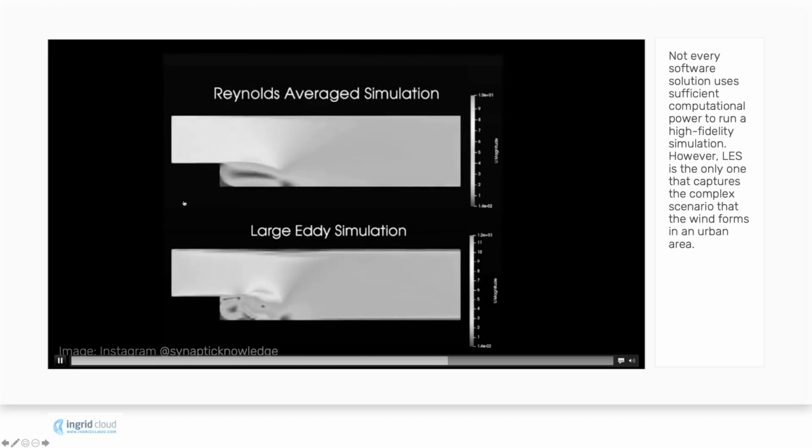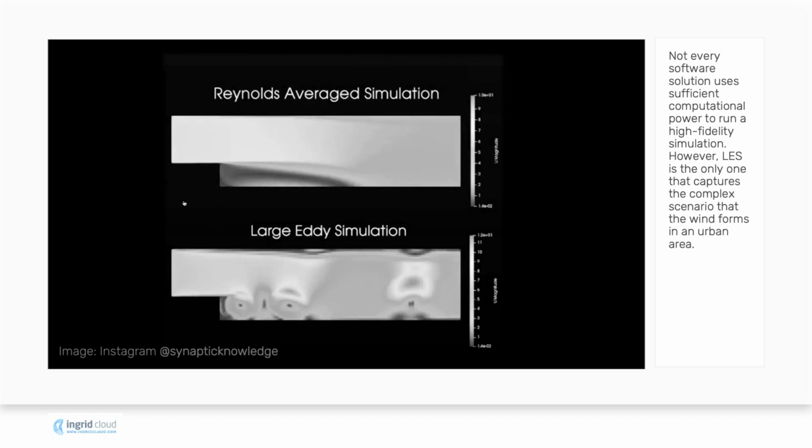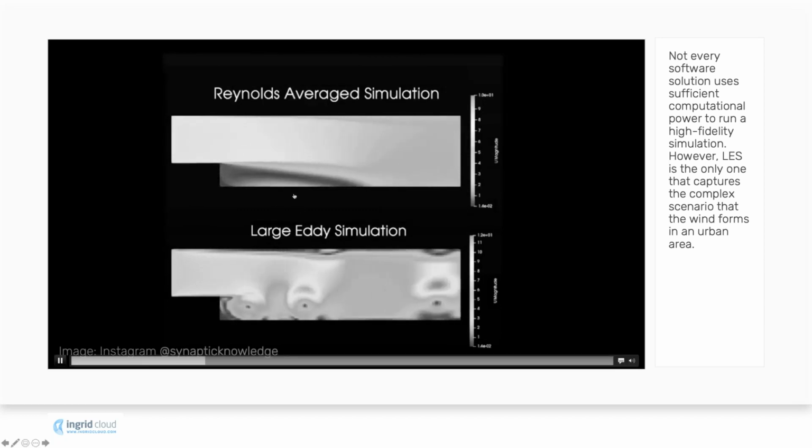And not all simulations are accurate when analyzing complex movement of the wind. So traditionally, CFD software does not resolve the small scales of a turbulent wind flow in order to reduce the computational cost, as exemplified in this movie above. This is called RANS modeling, Reynolds-averaged Navier-Stokes simulation.